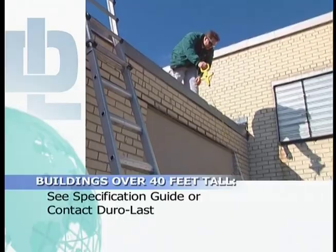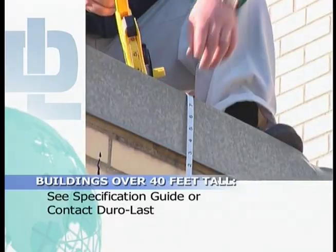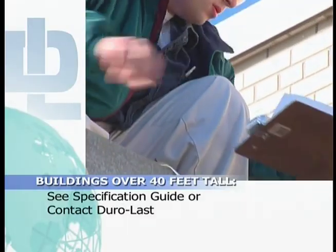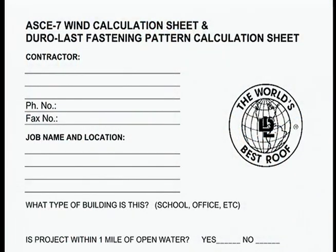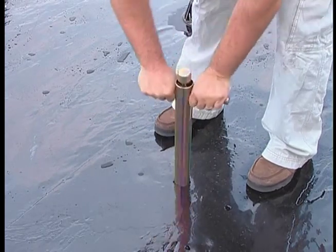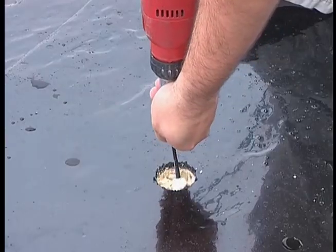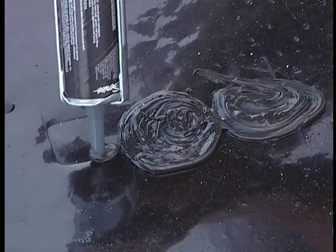Be sure to measure the building height to plan properly for wind uplift. In high wind zones or for buildings taller than 40 feet, refer to your specification guide or contact the Duro-Last Engineering Services Department for assistance. Also, fill out the wind calculation worksheet available on the Duro-Last website or in the Documents section of this DVD. You will also need to determine the types and number of fasteners required and what fastening pattern you will use. To do this, you will perform a series of core cuts and pull tests. The proper techniques for these procedures are explained in separate chapters on this DVD.